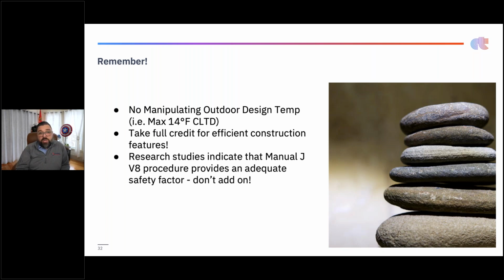So if you don't do an aggressive load calc and you add more to that, you can see how it just keeps manipulating the process further and further. And we do something we don't intend to: we oversize the unit, all right? Don't add any additional safety factor. There's so much built in between this and equipment selection I'm gonna show you, it's just not needed, okay?